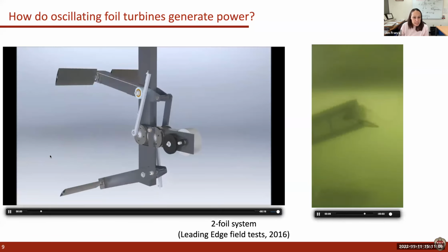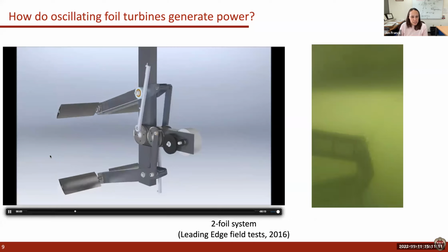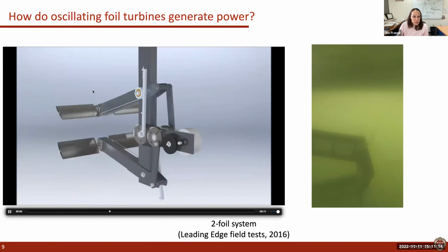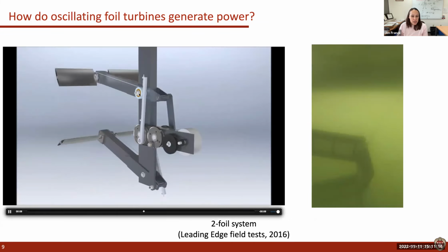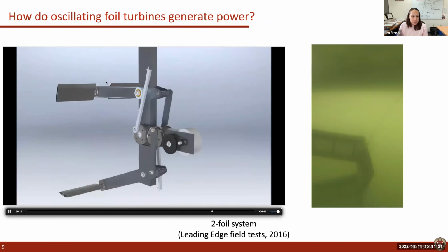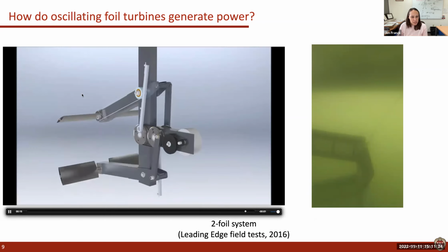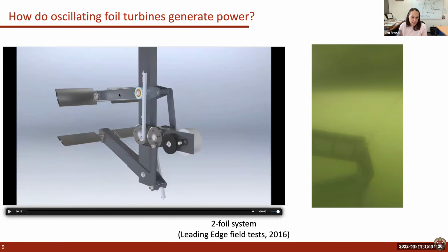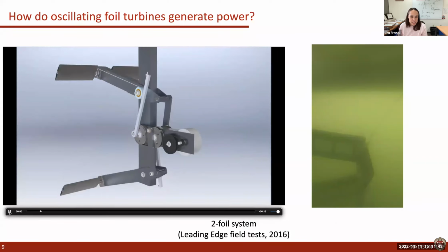And if you look at the mechanisms on the left-hand side video here, the two arms are coded to stop at a specific location. And then the pitch angle is mechanically linked to the heave motion, such that when the flow pushes it up, the linkages will push the foil downward. So that's how the completely passive system can operate. And then there's a sequence of gears to convert that linear motion into a rotational motion. I'll play that one more time.